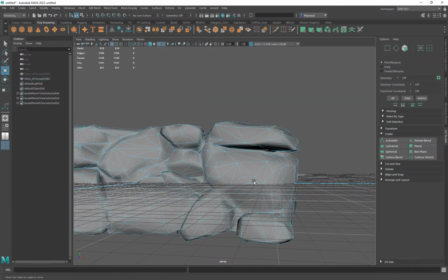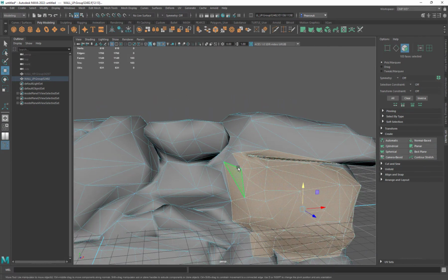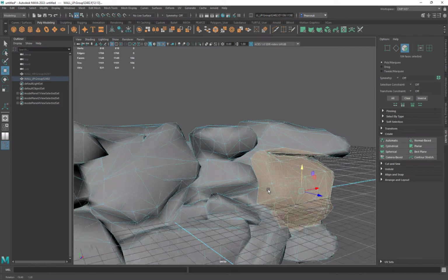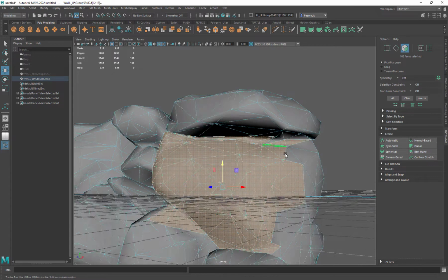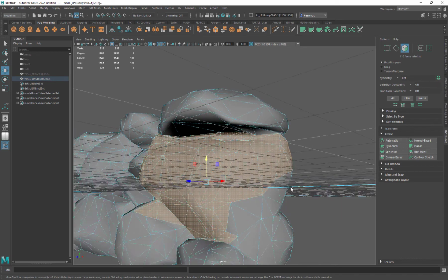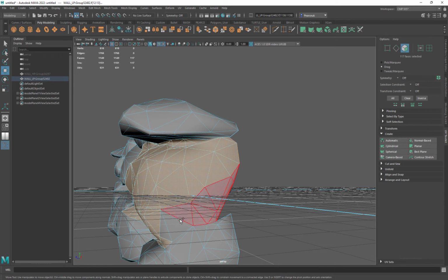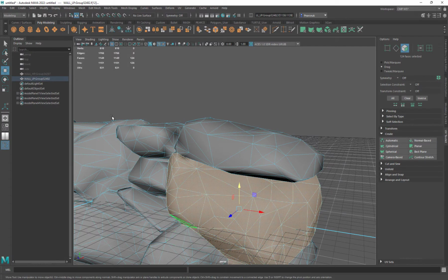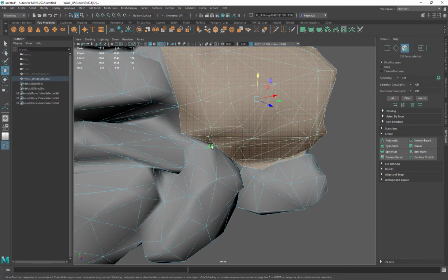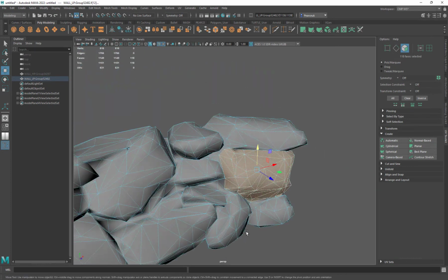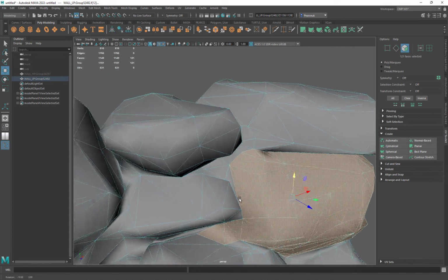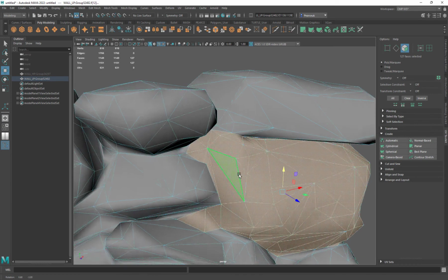So I'm just going to start by selecting kind of central pieces, and then I'm using the shift and grow selection, which is the greater than, or the full stop key, till I get to somewhere like there. And then I can drag select and drag deselect the areas that I want. I don't want those, it'll just hide the grid. Something like that.